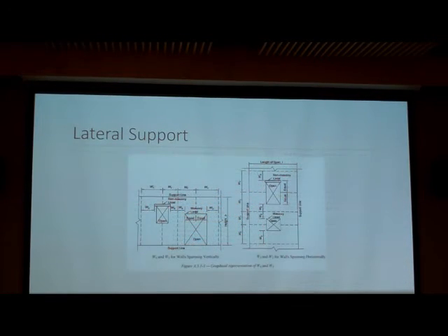and they are designed to limit the flexural tensile stress due to out-of-plane loads, and the requirements control maximum ratios for L over T and H over T. And then WS is the dimension of the structural wall strip measured perpendicular to the span of the wall strip, and WS shall be no less than 3 feet on each side of each opening. WT is the dimension parallel to WS from the center of the opening to the opposite end of WS. And to actually apply that, I have a picture.